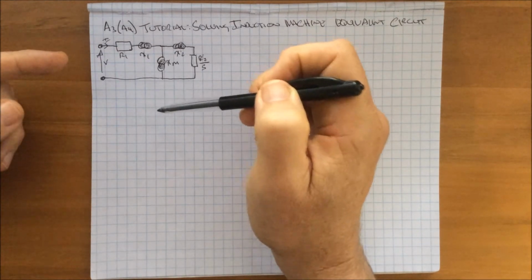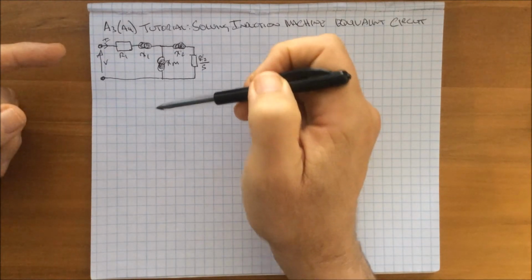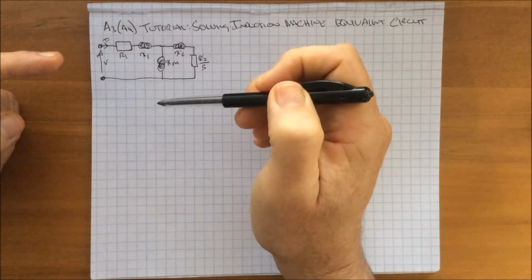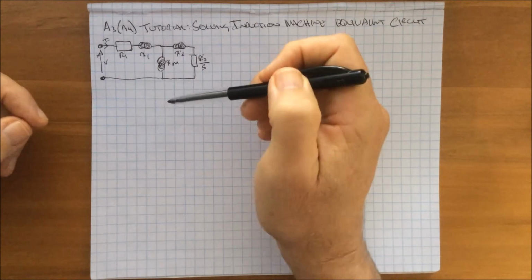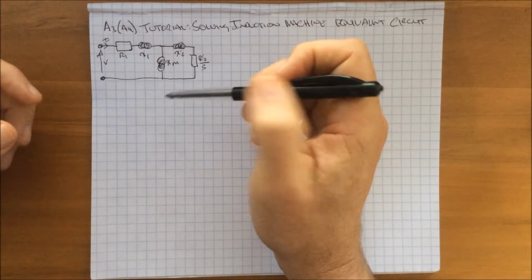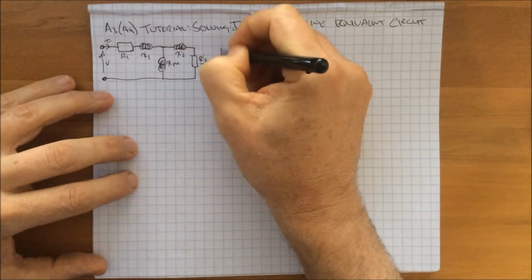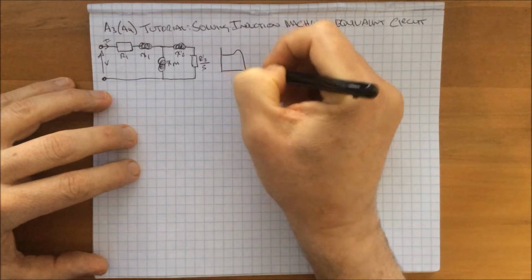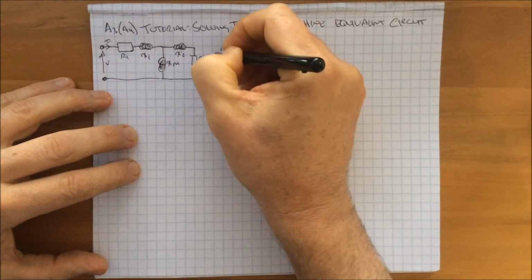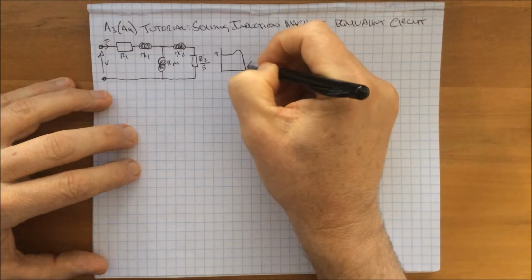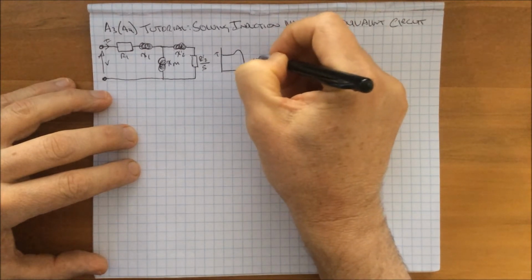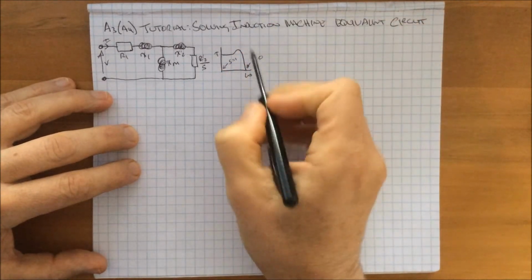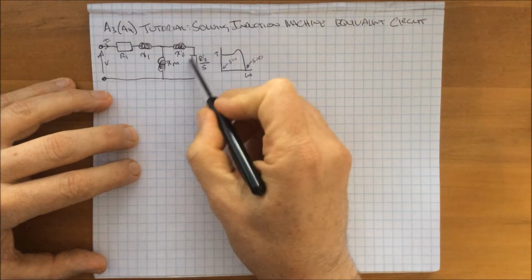The other condition we could do is we can lock the rotor, make the rotating speed of the machine equal 0 while we're putting power into it. Effectively, the machine is stalled, so as I said, the rotating speed is 0 or slip will be 1. If you remember our simple diagram for the torque speed response for the machine, which goes something like that. Here's speed, here's torque. At this point here, slip equals 0, and at this point here, slip equals 1. And this is going to have a significant effect on this value here.